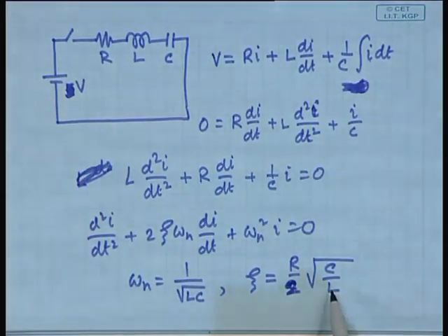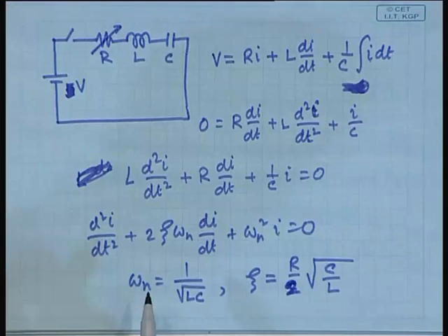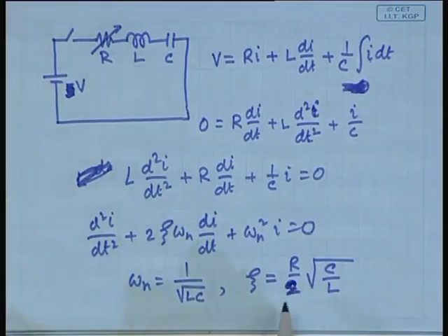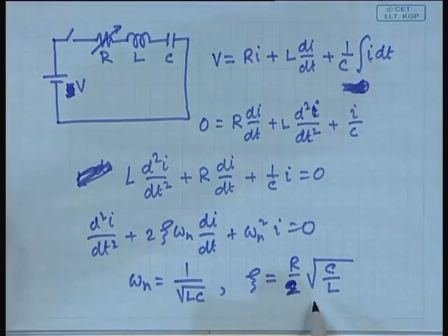Okay. So, if you have these parameters and say you have this as a rheostat, and if you smoothly increase it from a small value to a large value, then what will you see? No, initially it will be under damped, it will be an oscillatory solution, because the eigenvalues will be complex conjugate, and as you change it, it will slowly become firstly a critically damped situation when this is equal to exactly 1, and then it will become over damped, fine.